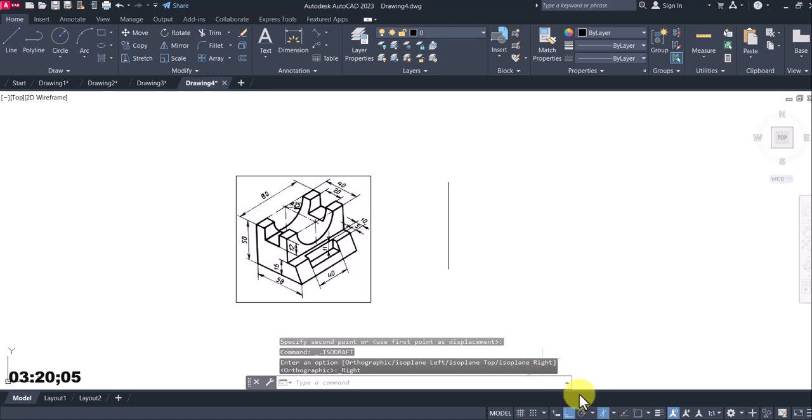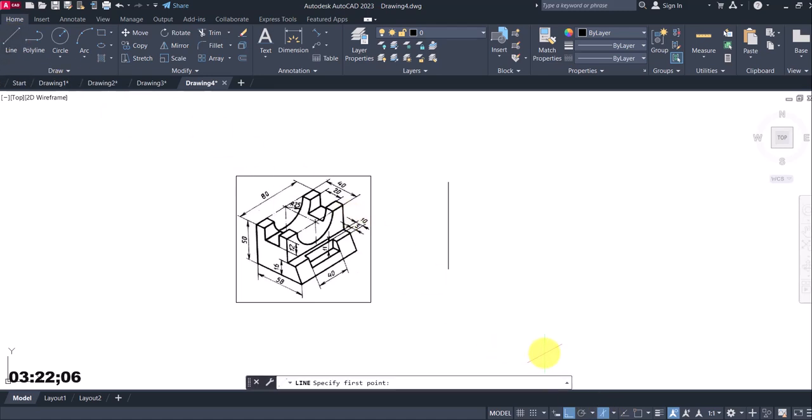All right, so I continue with my drawing. Because I've terminated the line at a point, I'm going to be using object snap to continue from where I stopped. All right. Now, I want to draw a line in isometric direction at a distance of 58. But looking at my cursor, I don't have that direction. So I'm going to switch my isoplane.